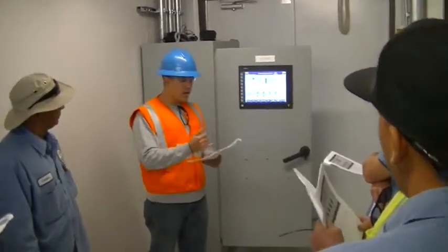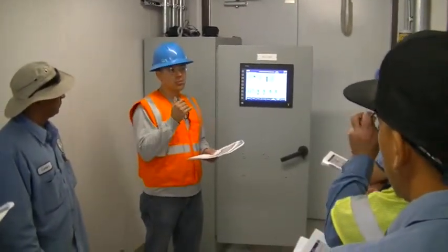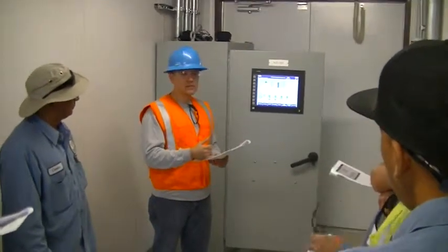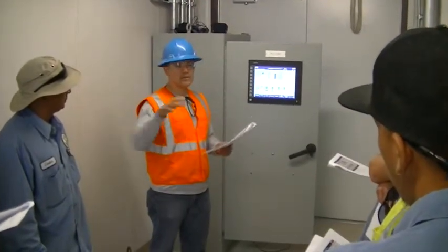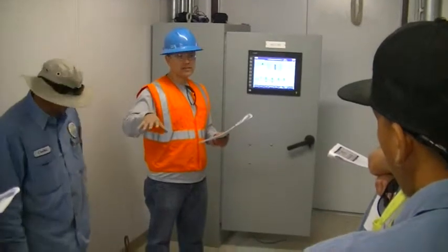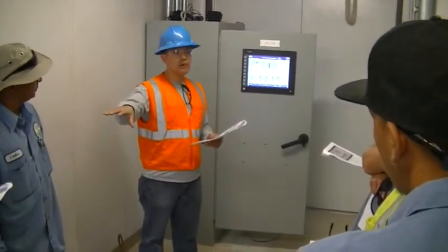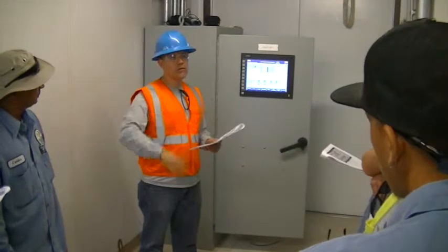Right. That'll also occur if the pressure out there drops below, I think it's 38, 36, or it's different for different pumps. But if it does that, it'll lock themselves out, put them in the backup PSHL mode, and work off the Mercoids.